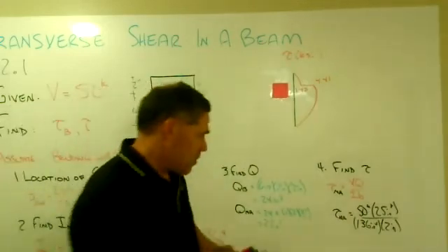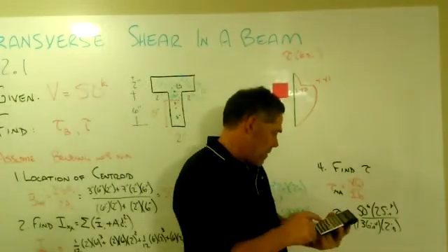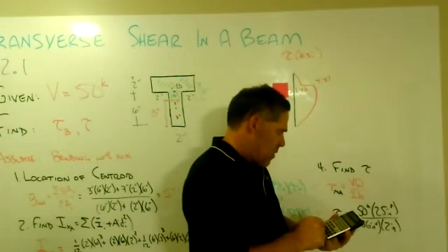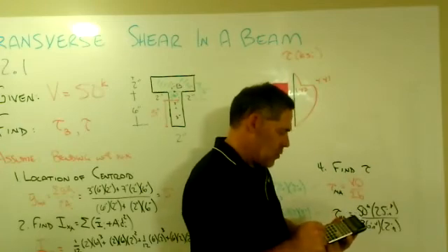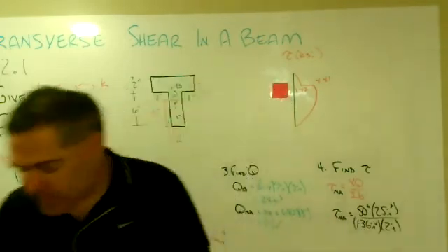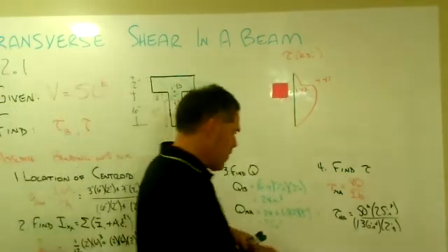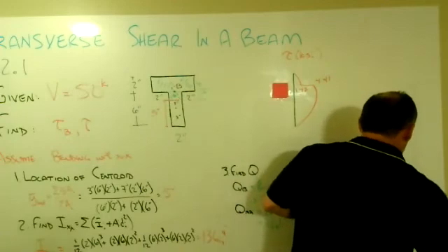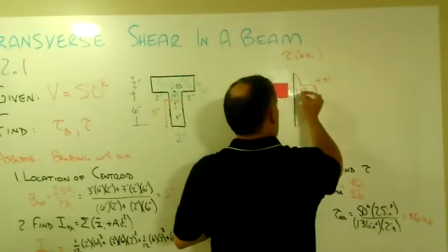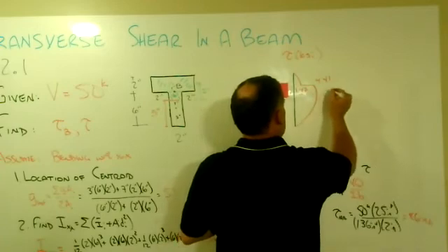Not going to vary a whole lot, but it will vary just slightly. 50 times 25 divided by the 136 divided by 2, 4.5955, or really about 4.6 KSI. Right? And so that would be the maximum.